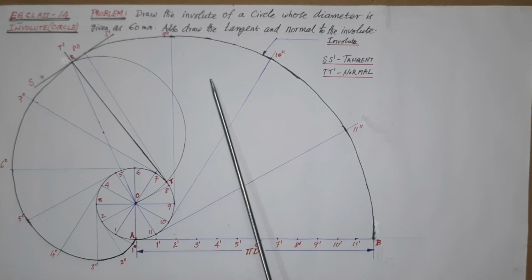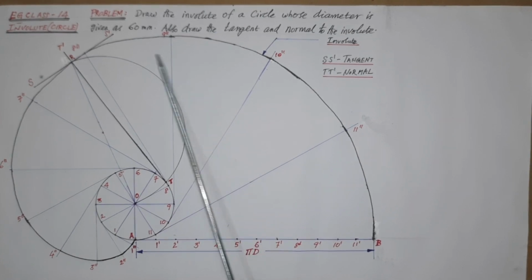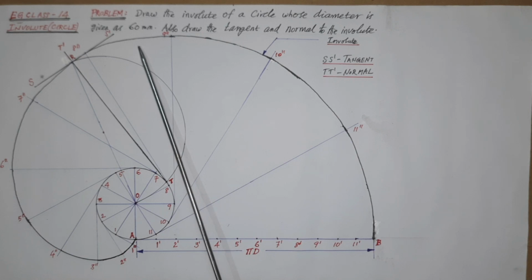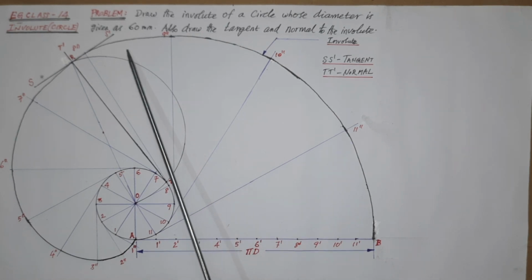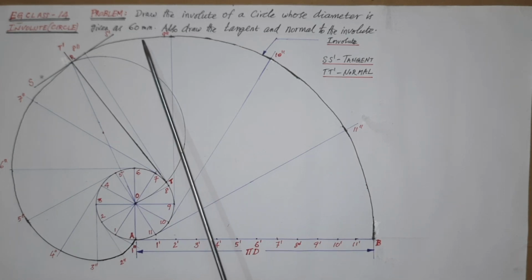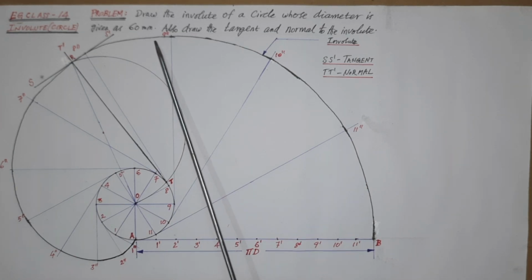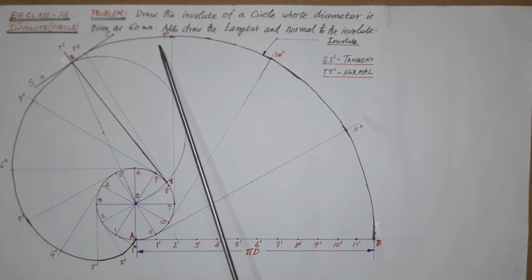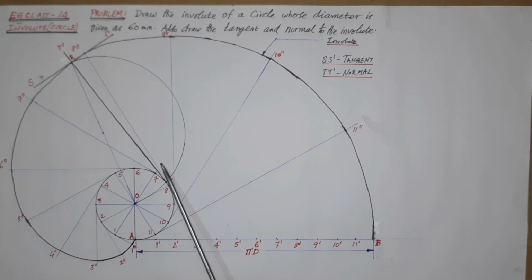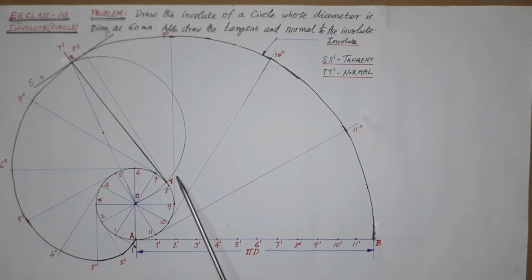As already told, remember once again, listen whether diameter or radius is given. Always a circle is to be drawn based on radius only. If diameter is given, convert into radius, and hence it is 60 divided by 2, 30 mm. Based on the usage of data, the problem is completed and the final drawing is shown here. This is only for immediate reference. However, the drawing is to be done only by step-by-step procedure for easy understanding.